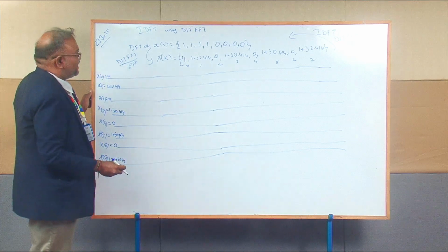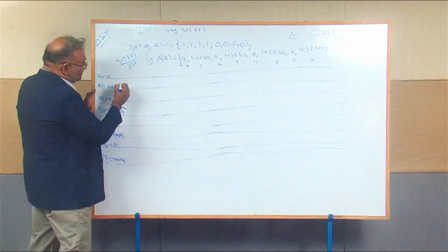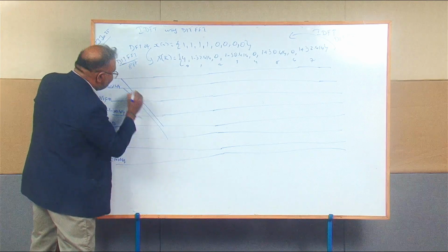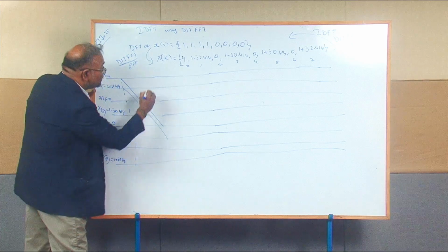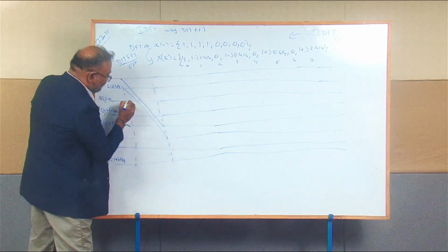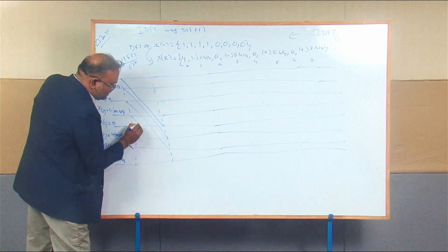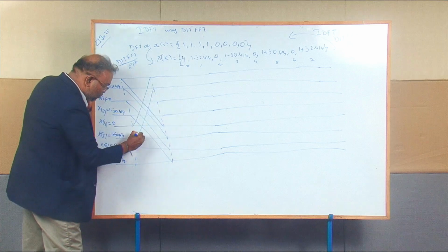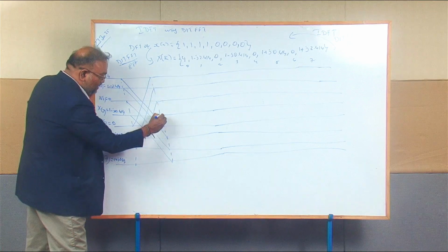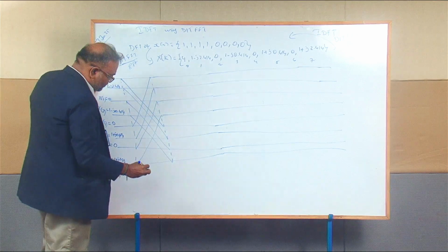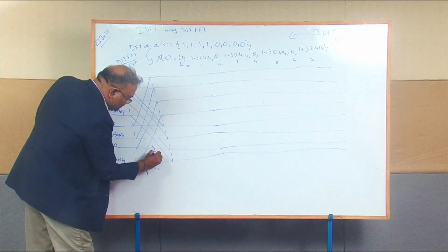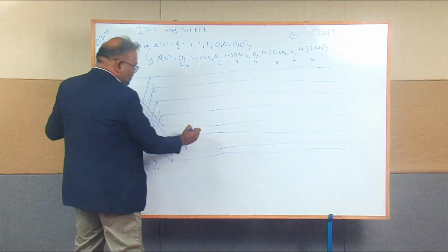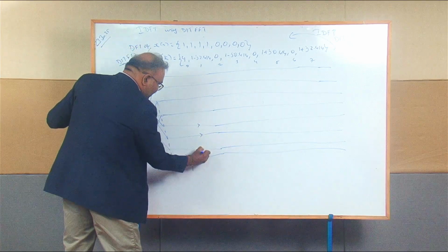So we can finish the diagram first. First stage is 8 point. So 8 point starting from first and fifth line, second and sixth line, third and seventh line, fourth and eighth line. Now reverse process from 5 to 1, 6 to 2, 7 to 3 and 8 to 4. 4 minus 1 will be there. Twiddle factor will be afterwards. So leave some space for initial calculation.